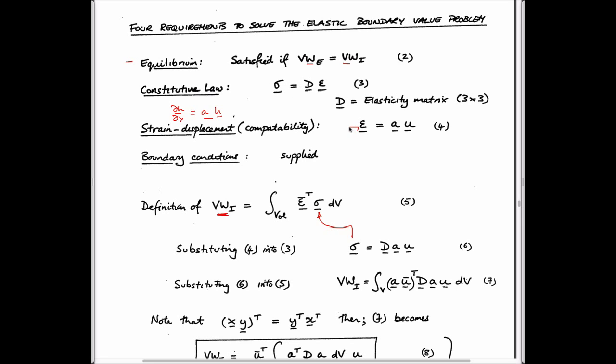What happens if we, and this is, just as we said, strains or displacement gradients linked to nodal values by some operator. We don't know what the operator is yet, but we could, for instance, put this quantity in here. If we did that, we'd get the fact that stresses are equal to the elasticity matrix multiplied by AU. That's exactly what this is here.